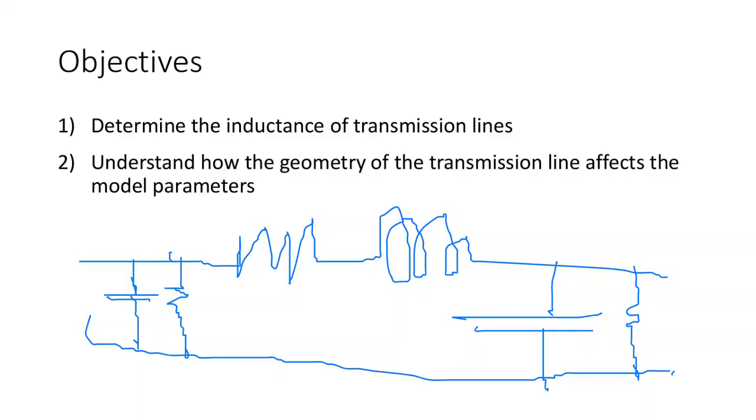We have leakage current. Therefore, we draw this conductance. We have power losses. So why do we get this resistance here? Because of the power losses. Therefore, we need to write resistance to present it. Otherwise, we cannot solve it. So we need to solve this one.